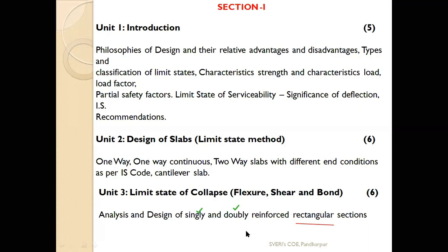You know what the neutral axis is, as you have studied in the second year already. Every fiber or molecule on the neutral axis does not experience any stress or force. That is why it is called a neutral axis. The elements above the neutral axis generally go into compression, and the fibers or molecules below the neutral axis generally go into tension.